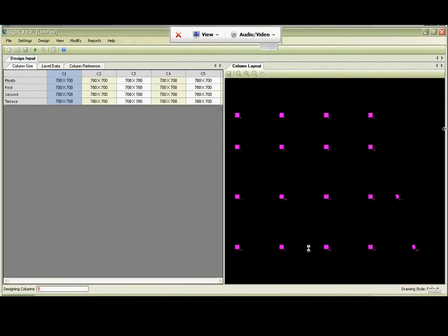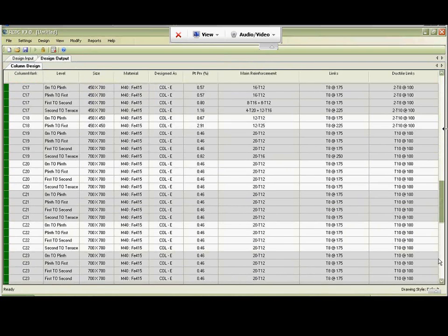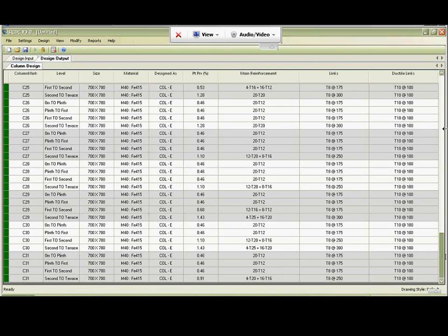Once I've defined the load combinations and basic load cases, I say OK. The software will now create the combinations based on the combination definition, and design all the columns up to bar arrangement. So it will optimize, perhaps give a combination of diameters, etc. and do that for all the columns in a matter of seconds. So I think we have around 25-30 columns here over 4 levels. So all the columns are designed and a basic design output is displayed to the user.